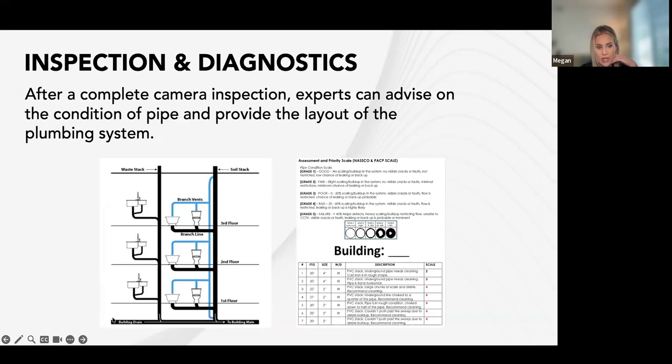And with the inversion equipment, you have to line through and then go in and cut a hole and reinstate that liner. Okay. So as I mentioned, with that inversion liner we're able to do a lot of pipe installation at one time, but it is going to be a straight run. So if there are a lot of connections, or for example, like this, we're going to probably recommend the epoxy coating method or brush coating. We're actually able to go in there, depending on the condition, if there's cracks, all of that goes into play on recommendations.